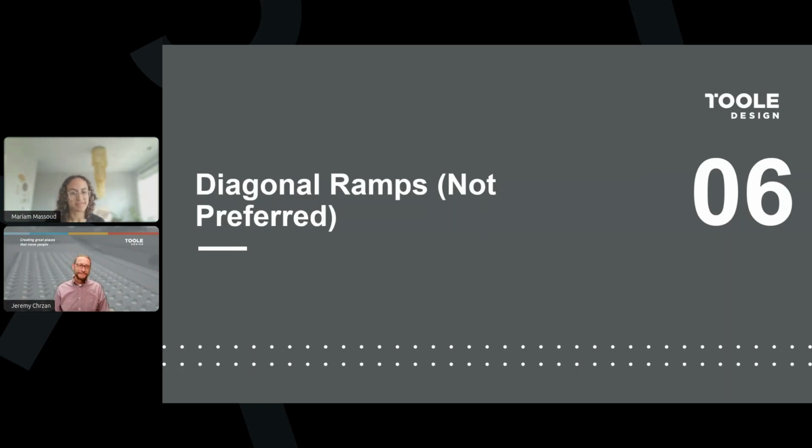Okay, let's see here. There's a photo of a ramp with brick or a stamped brick pattern on the ramp itself. Is that acceptable? It is not preferable. PROWAG requires surfaces to be firm, stable, and slip resistant. Concrete is going to be preferable for a curb ramp. Asphalt or concrete are going to be preferable for a shared use path or sidewalk. And as Miriam was saying, the brick isn't allowed on ODOT projects.